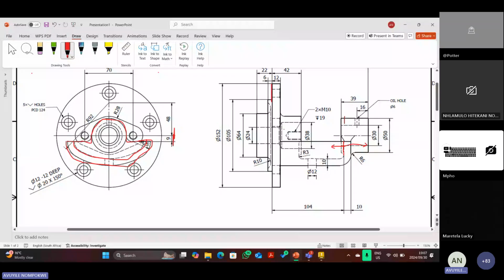But I did mention to you guys that this distance here is 4 millimeters. This one here, it's 4, right? Assuming that since we're here, we have to extrude by 4 coming to this side, and then now by 39 minus 4 going to that side.